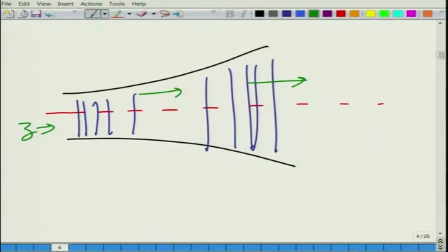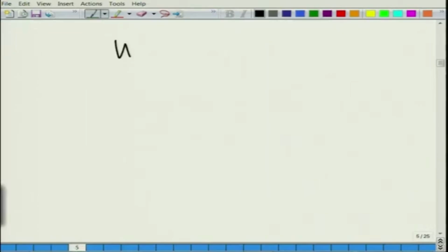We will do some special cases like exponential horns and conical horns, and a few cases for which the analytical solutions are well known, and then go for more advanced mathematical modeling this week, like the segmentation approach and possibly the matricant approach, perhaps solve a few problems for the transmission loss, and then end this particular topic's presentation by introducing things like perforated elements, although the detailed analysis will be done in the later lectures. So, let us begin now with what is known as Webster's horn equation.